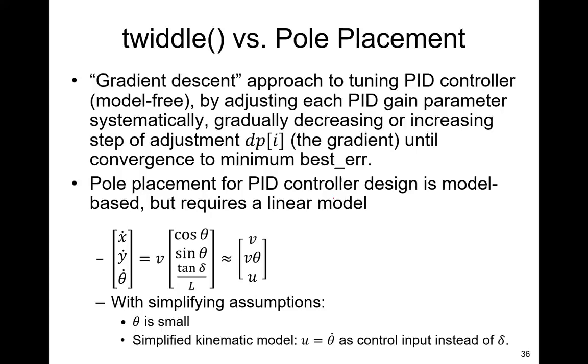You must tune it with a heuristic rule because of the nonlinearity in the system model. Therefore, twiddle is universally applicable to any system by gradually adjusting the parameter with adaptive step size dp until convergence to a minimum best error.